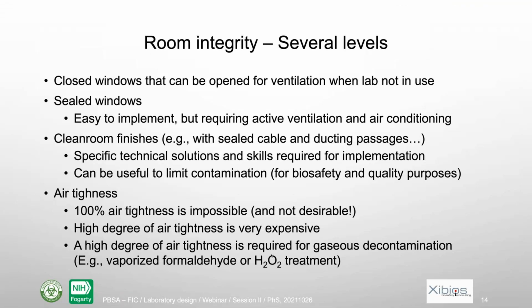So with respect to room integrity, you have several levels. The normal level, according to core requirements, is to have the lab with the windows closed, for instance, and door closed when you work, but that's all. Then you could have an additional level if you have sealed windows. In that case, of course, you cannot open windows, for instance, when you don't work in the lab, but that's very easy to implement. But for that, you necessarily need some active ventilation and air conditioning.